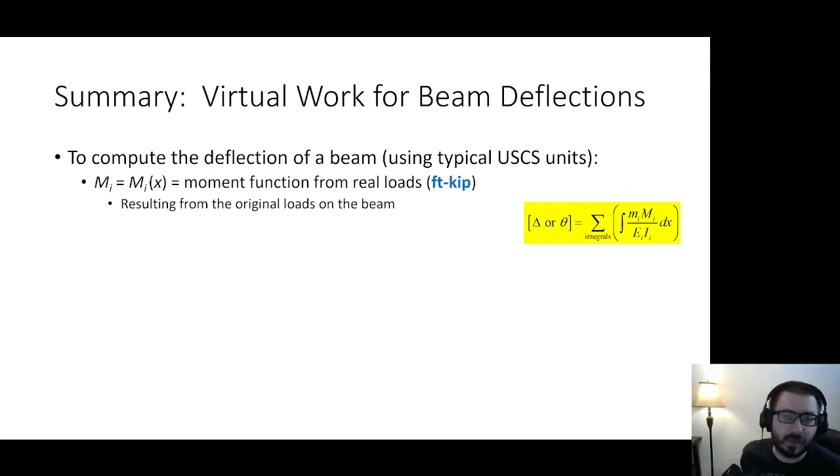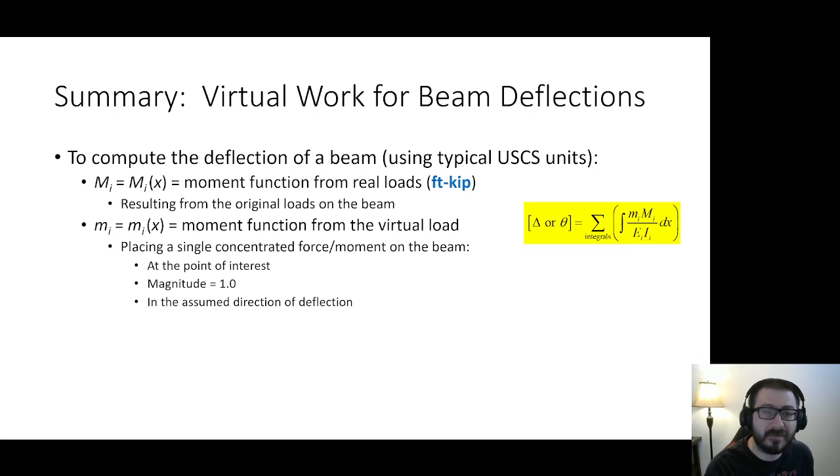So we have real moment functions and we have virtual moment functions. If you remember, we had an assignment where we had to compute moment functions and then plot the shear and moment diagrams in Excel. This skill is going to become really important when we compute deflections, because we're going to need those moment functions and we're going to need to integrate them. So we're going to have a set of moment functions for the real loads and a set of moment functions for the virtual loads.